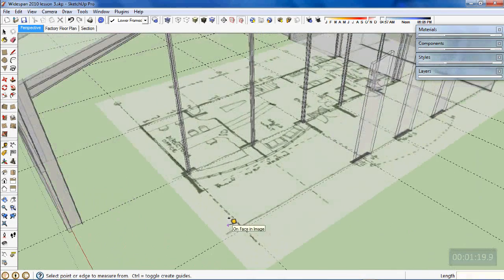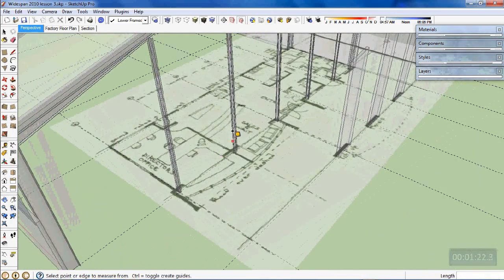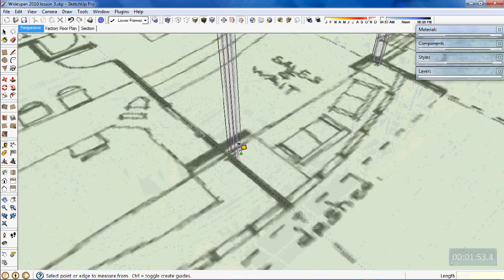Now there's one more I need to put in, and that's the grid line that this column is on. I actually want to check that I have put that column midway between these two grid lines, because we've got a glass curtain wall going at the front here in a nice curve sort of arrangement, and I'd like this column to be central with that glass curtain wall. So I'm clicking on this set out line and going to the other set out line. It's 8475, so I'm coming back and I'm going 8475 divided by 2. Okay, and as you can see, our column isn't exactly on there.